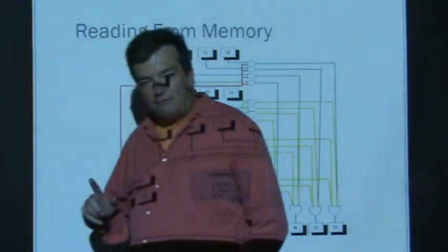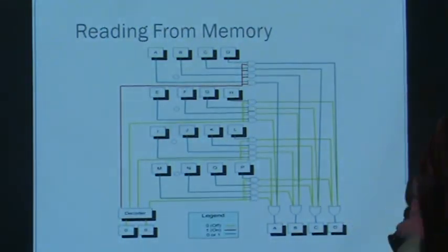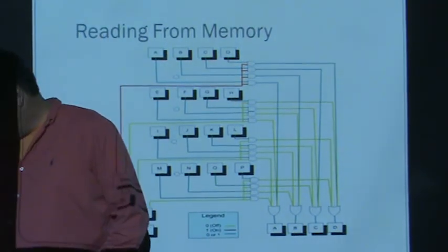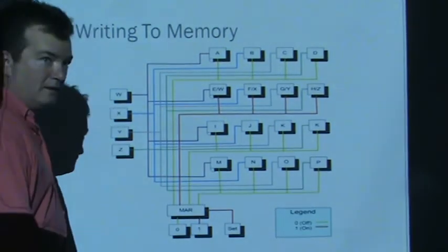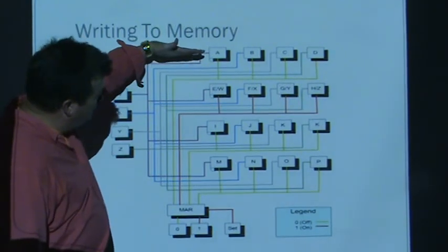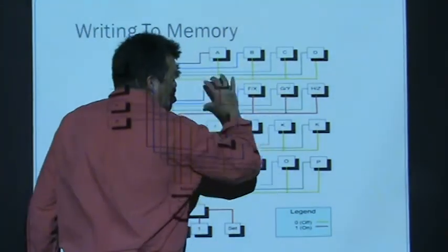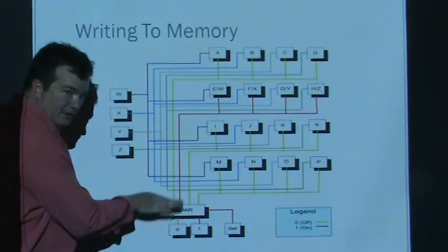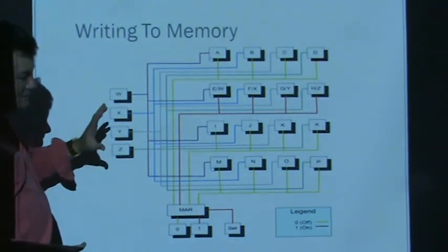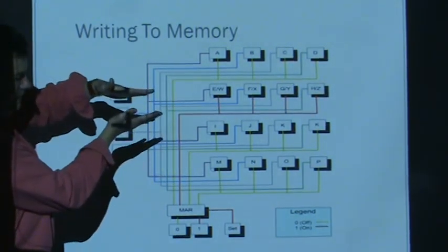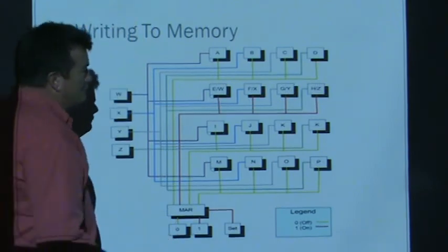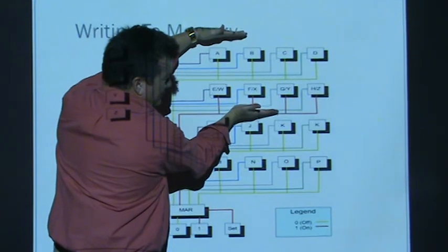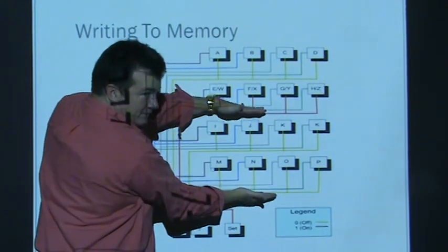would actually be faster than reading from a field. So suppose, for example, this is again a small version of memory. But suppose when we want to write to either nibble 1, nibble 2, nibble 3, or nibble 4, I had to put a number between 0 and 3 here to pick which one. Suppose we have the concept of a page. Well, what is a page? A page is a larger group of data. So suppose I decided to make a page size of 2 nibbles. So this is one page, and this is a second page.